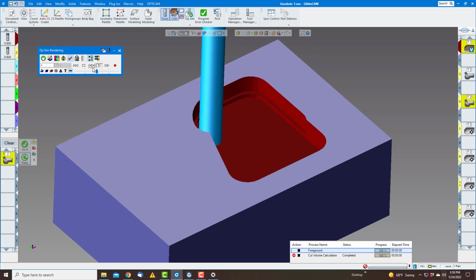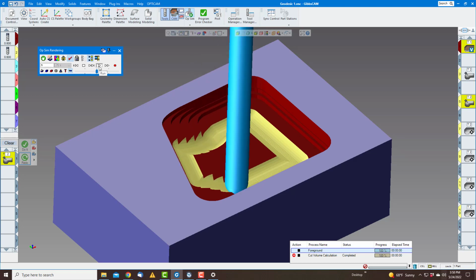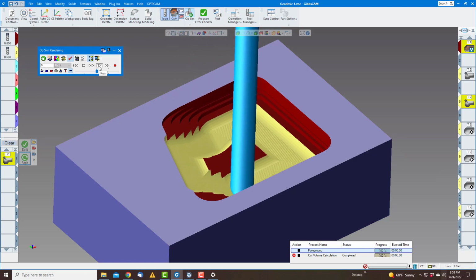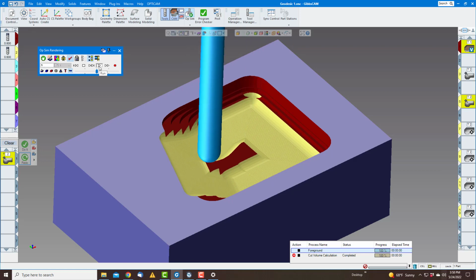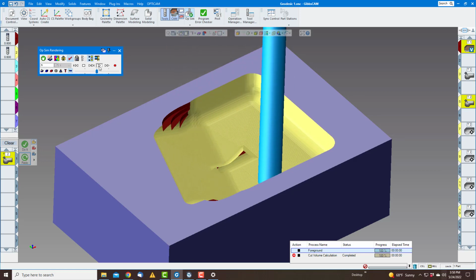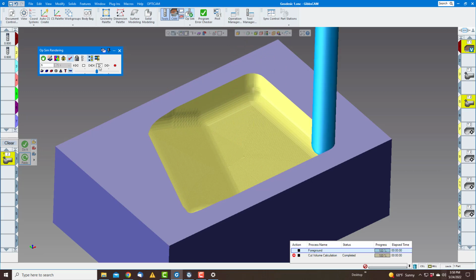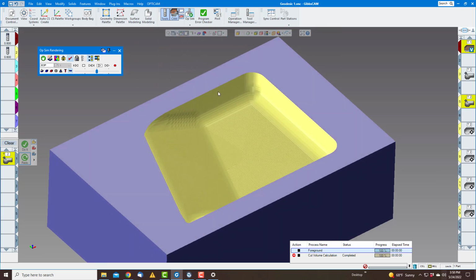we'll do the 1/2 inch end mill again. And this time we're kind of doing in the middle and going to the inside and outside at the same time. This also cleans up very well. Looks very good.